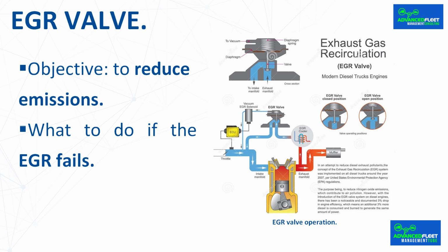When a diesel car drives a lot in the city and the engine frequently rotates at a low engine speed, more carbon is produced, so diesel cars that do a lot of city driving and not much highway driving are more prone to have their EGR clogged.